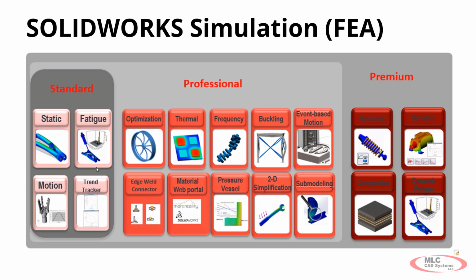As you go into professional, you start answering some more complex questions. If you're taking in the effects of thermal loading, where you have heat transfer, you have that kind of study. Frequency, where you're answering the question, if this is attached to a motor, is the vibration going to cause failure prematurely? You have buckling analysis: you have long cylinder components that can buckle, is that going to cause failure? You also have tools for optimization to help automate those designs: how can I change these dimensions to get the design goals that I want? So these are the main ones in professional.